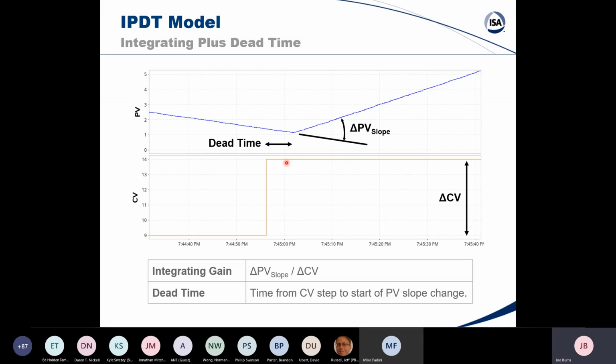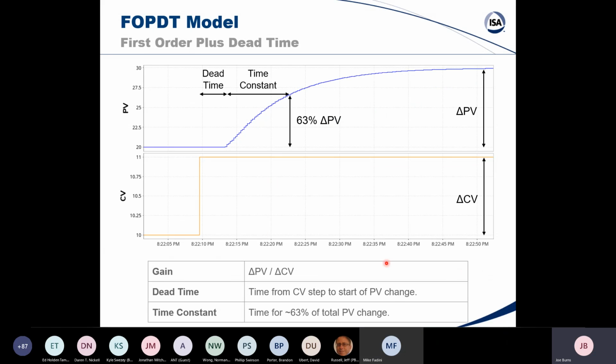So how would that affect the constants in the PID? We haven't gotten to the PID tuning yet, but it would affect our process model, which is how we're going to derive PID tuning values. In that case, the time constant for the flow control valve is going to be really short, and we'll see how these model parameters get used to calculate the PID tuning values. Okay, thanks. Sure.